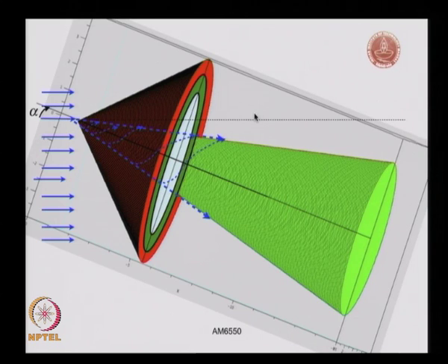About this, the shock wave angle is varying as we make different phi angles. If I make a certain phi angle about the axis of this cone, then my shock wave angle will also change, which is not the case for the axisymmetric case we did. So, the shock wave angle is also a function of the phi angle. We have a shock wave like this, right.